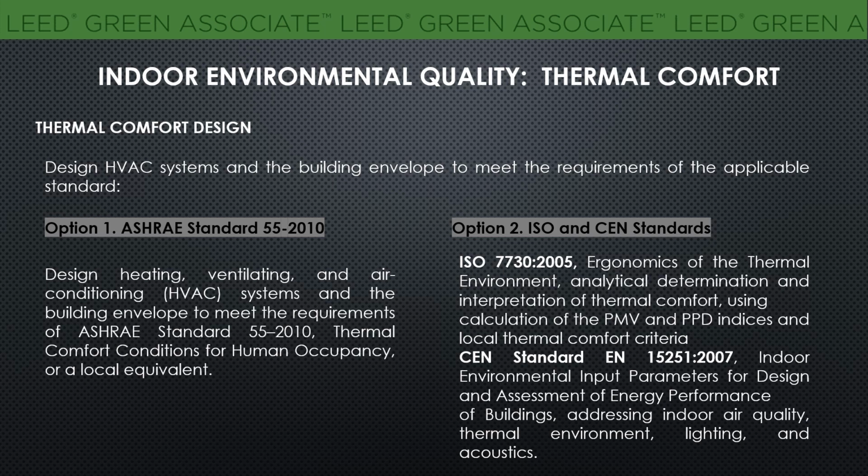As I mentioned, there are 2 options for achieving the requirement thermal comfort design. In this particular credit, we will discuss 2 standards for design of the HVAC system and building envelope. Option 1 is based on ASHRAE Standard 55-2010. For the design of the HVAC system, HVAC, as you know, is the heating, ventilating and air conditioning system, and the building envelope needs to meet the requirements as per ASHRAE Standard 55-2010, thermal comfort conditions for human occupancy, or a local equivalent.